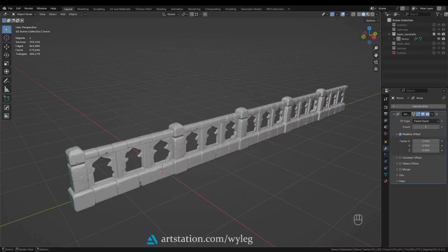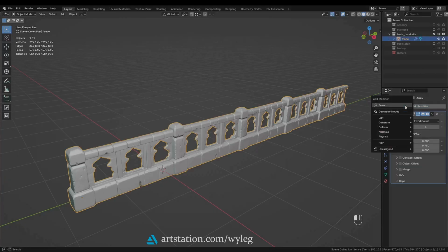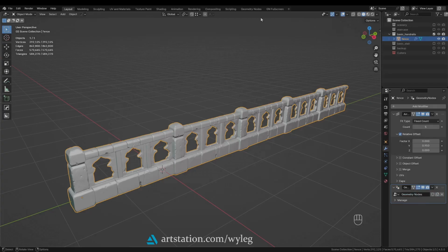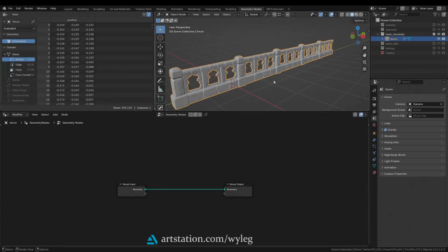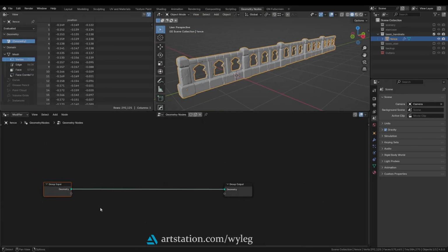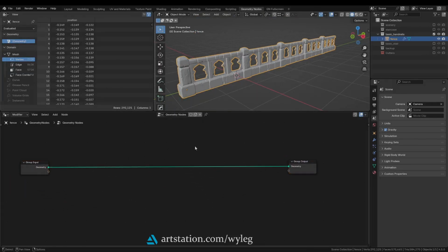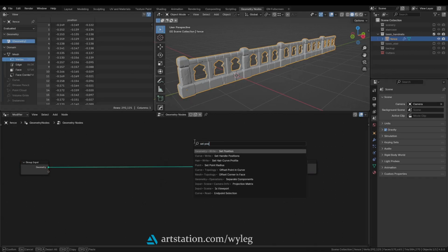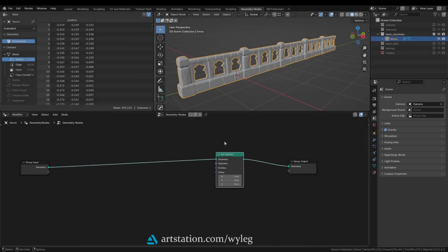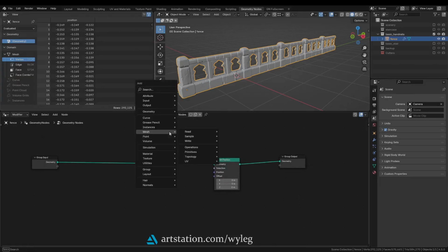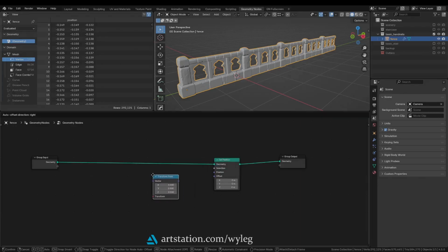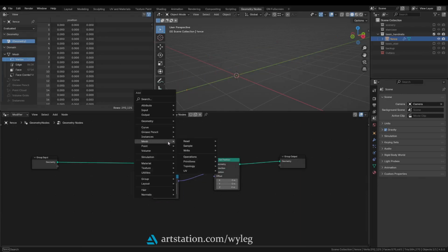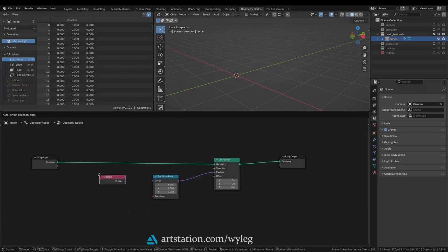Alright, so how do we make a shear modifier? Turns out the shear operation, or the skew operation as it is called in mathematical papers, is a trivial mathematical operation that transformation matrix enables us to do. Trivial means that we don't need to dive headfirst into linear algebra, we can just barely wet our feet. With recent updates in Blender GeoNodes, we can use transformation matrix to apply changes to our mesh. So let's create new geometry nodes modifier for our object.